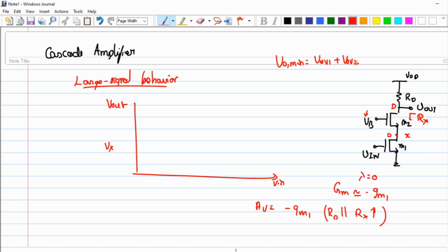I can use a MOS. We know that when I take a MOS transistor, basically the current has to flow, okay? We also know what the impedances are that I see when I look across each of these points, right? When I look across the gate, it is infinity. When I look across the source, it is 1 by gm, an approximated value. When I look across the drain, it is r0, okay? Now, which point could be fixed in order to have a very high gain, and also make sure that the currents are flowing through the device, through the terminals that you are choosing?